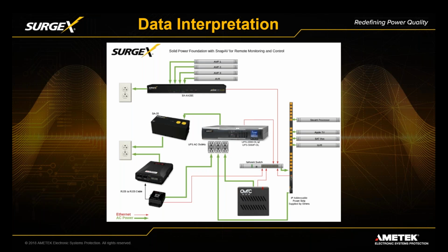But use some sort of level of control, but don't just use the IP addressable product. Don't just continue to react to issues where products need to be rebooted. Try to figure out why they're being rebooted, and then ensure that you reboot less. If you put surge elimination at the wall outlet, and then you bring in clean and stable power, the two critical benefits to an online dual conversion UPS are stability of power being number one, and then power with no interruption, no transfer time to battery in the event of a power outage or a severe undervoltage or overvoltage. We need to continue to supply stable power to the very sensitive equipment in the IP addressable power product.